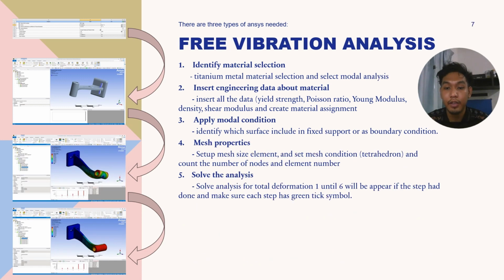And the last step is free vibration analysis. For the first step, we need to create a modal analysis system and then apply it to the assembly parts. Select all the engineering data, properties, and material in the data properties. We repeat the same step to identify the material selection as titanium metal. The second step, insert engineering data about the material: all the data, its strength, Poisson's ratio, modulus, density, shear modulus, and create the material assignments.